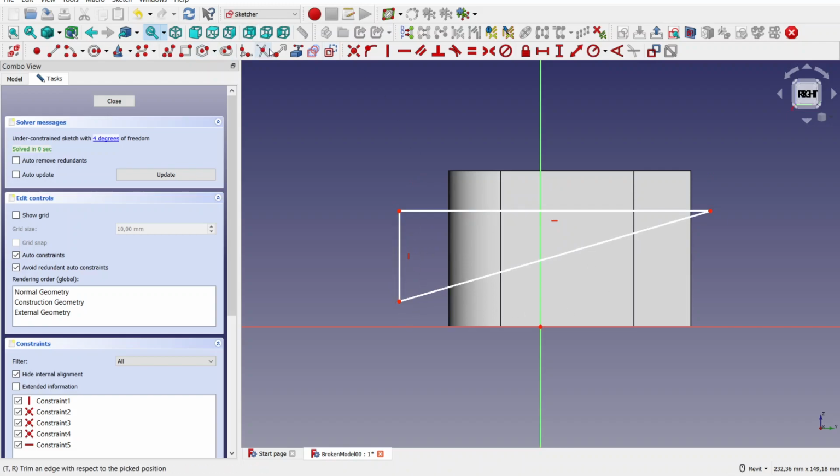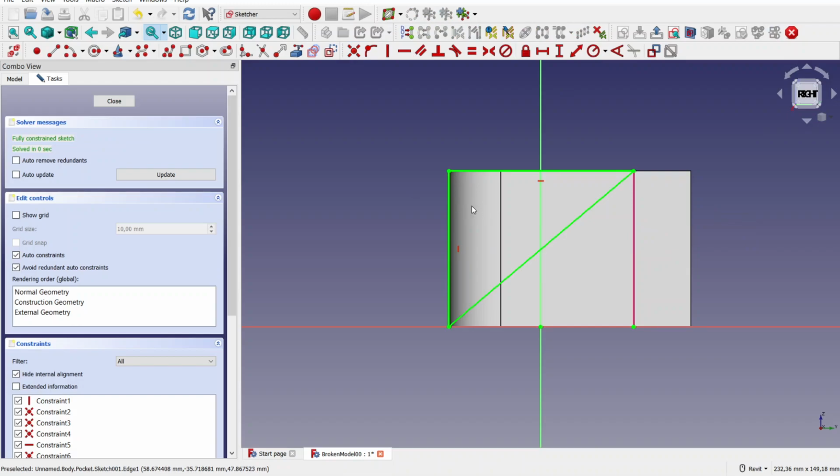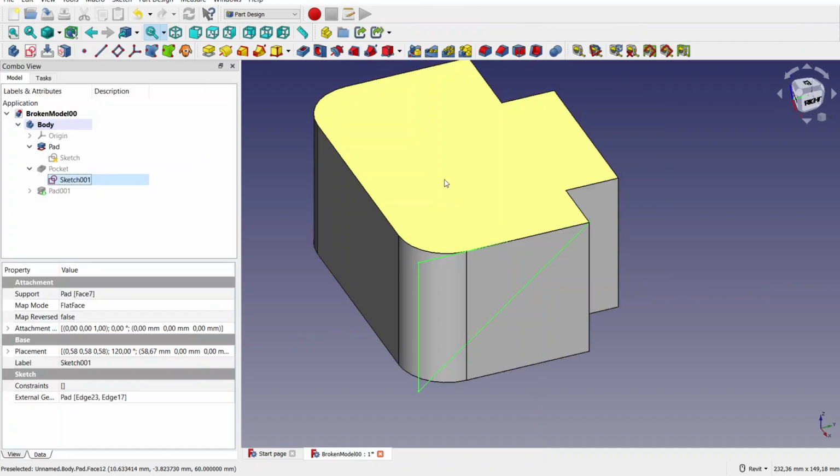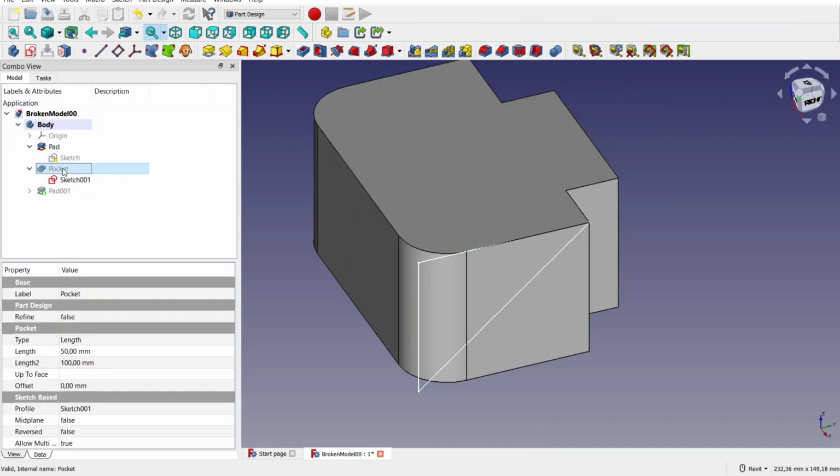And what I'm gonna do now is again use this. Now this is not proper workflow, but then again proper workflow is something you would set up better from the beginning using datum planes. I'll go into the proper way to do that in another tutorial. But for now, I'm going to fix it like this, which is also fine if you don't plan on changing it afterwards. You just need to be aware that you're linking to generated geometry, so every time you change the original geometry, it's going to give you issues in a new one.